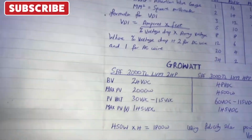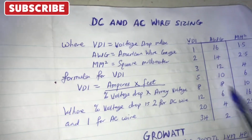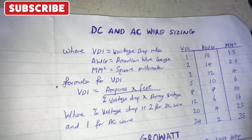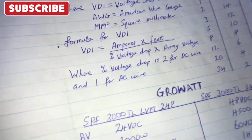So still using our VDI chart, what we have is 17.08. There is no 17, the nearest one is 20, giving us 4 AWG and 25 mm. So any way you do it, you are on the right track.